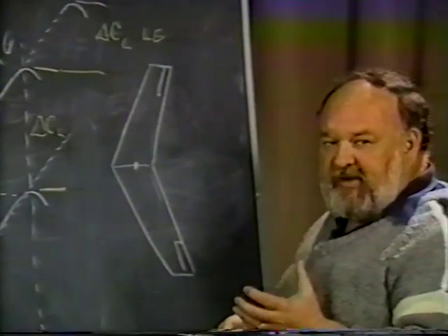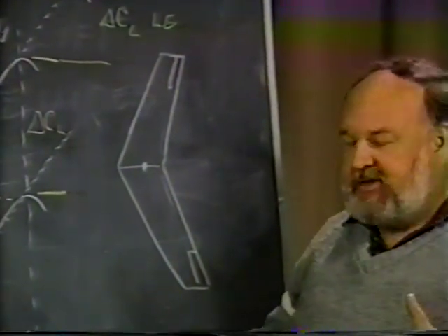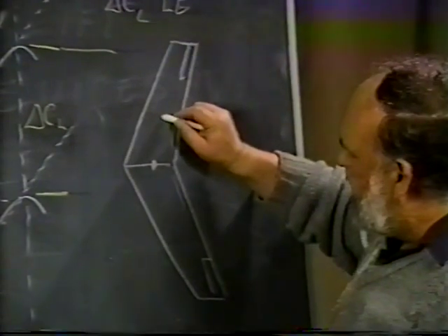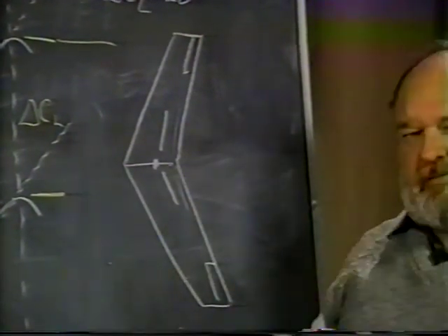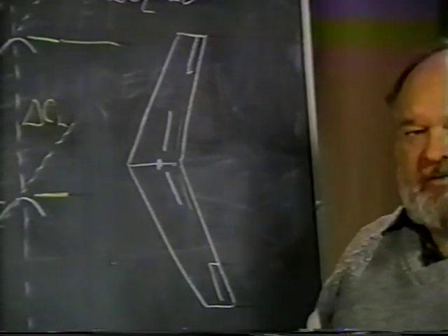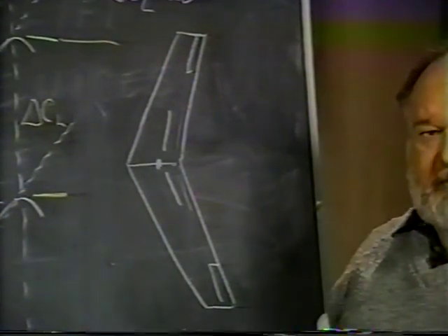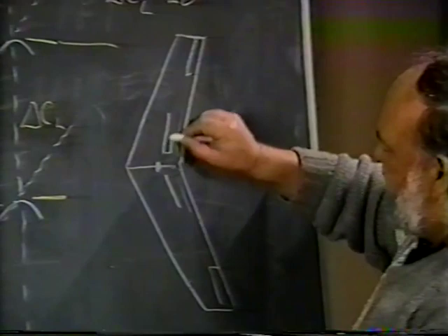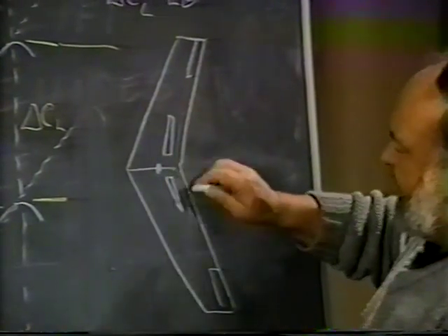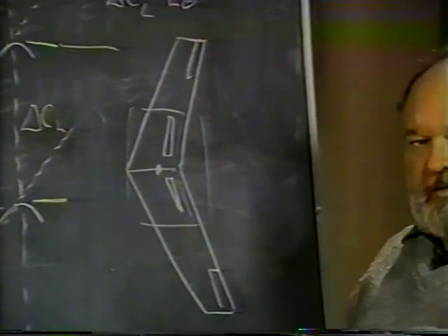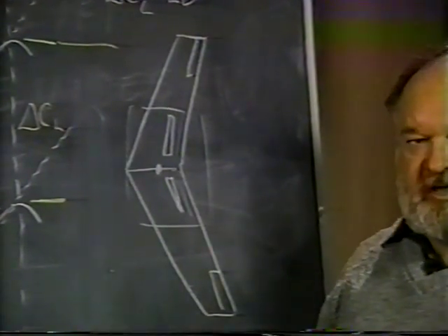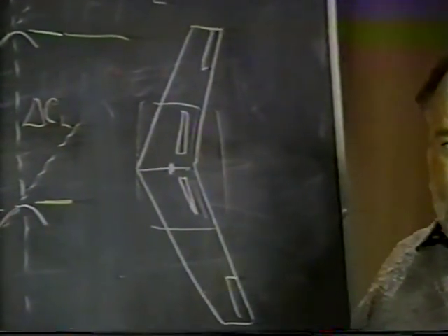But they took the split flaps, because it's the one that has the least amount of pitching moment, and they moved it somewhat forward on the bottom of the wing. I don't remember the exact numbers, but I think the hinge line was somewhere around the 60 or 65% chord. And by deflecting the flaps down in here, they got an increase in CL in this region of the wing with minimum pitching moment changes, ones that they could tolerate.